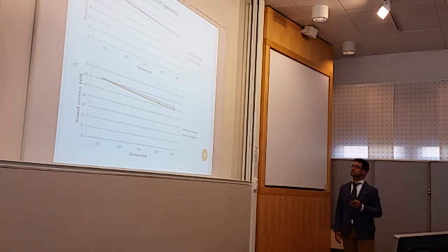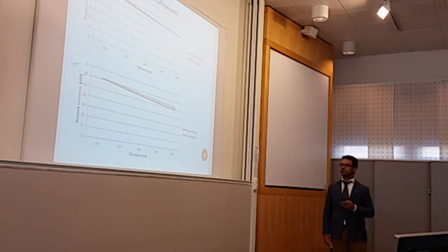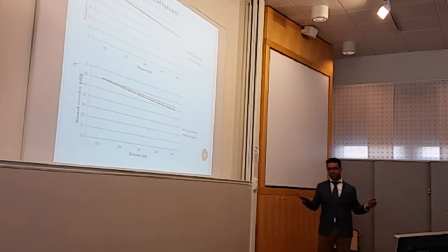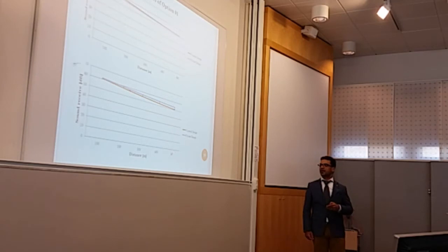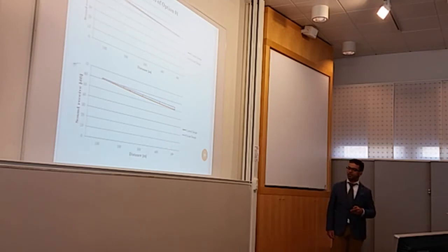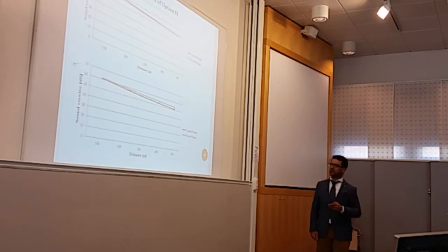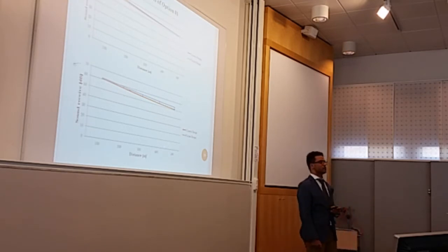So it's logical that the future design will provide less noise from the turbine. But for option 2, because we are increasing the sweep area itself, even though we are also increasing the hub height, at 500 meters from the base of the wind turbine the sound will increase by 4%.